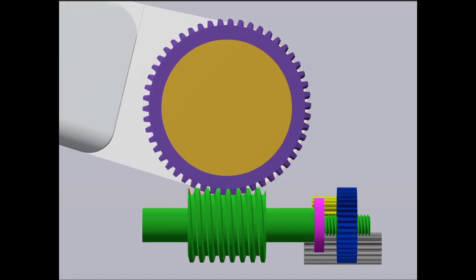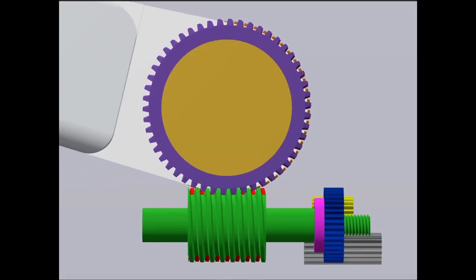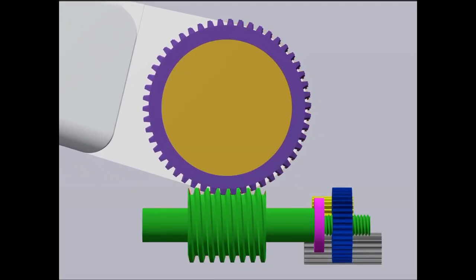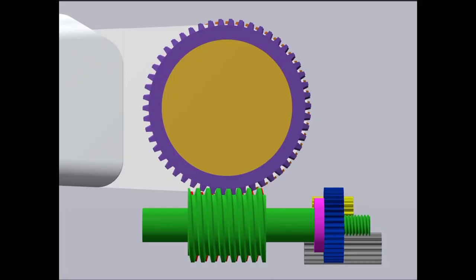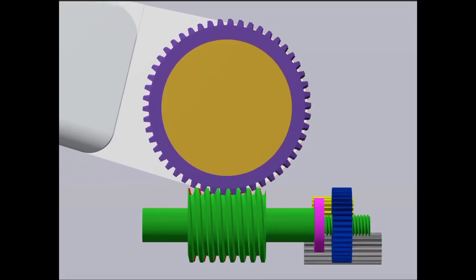When the washers are compressed by contact with the proximal gear, stiction holds the proximal gear stationary relative to the worm gear, transmitting torque to the proximal link. When the proximal link finds an obstacle, a predefined external force limit is reached, causing the proximal gear to slip and disengage from the washers. At this point, motor torque is transferred solely to the distal link. Stiction between the worm wheel and the worm gear prevents backdriving, keeping the proximal link stationary.